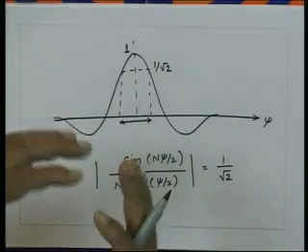So, for an approximate calculation of the half power beam width, we can find out the directions of the nulls. From there we can find out the beam width between the first nulls, and then we say the half power beam width is approximately half of the beam width between the first nulls.